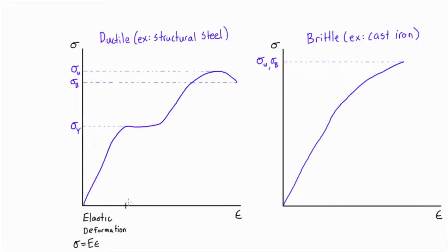Now if we keep applying our tensile force here, and we get a strain that's going to cause us to reach this yielding stress and then keep going, what happens is in this region we get yielding, and basically what's going on is we get a significant elongation of the member with actually very little extra applied load. So going back to this first section here, where I said if we load the beam, we're going to follow this profile going up and up like that.